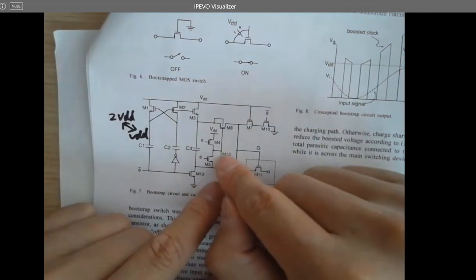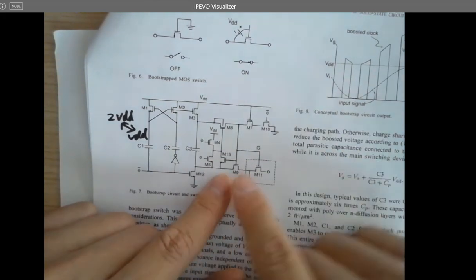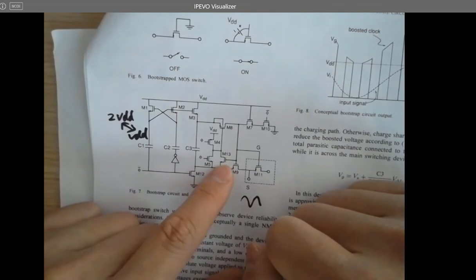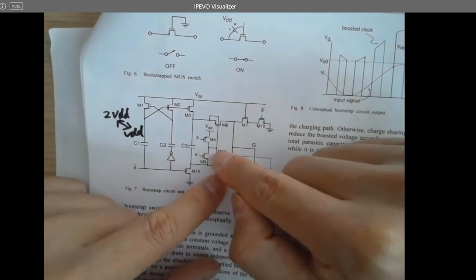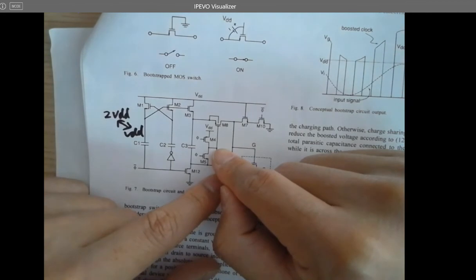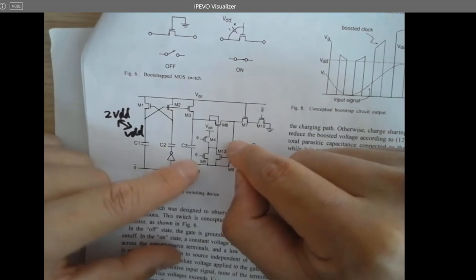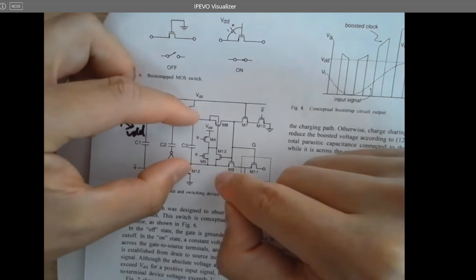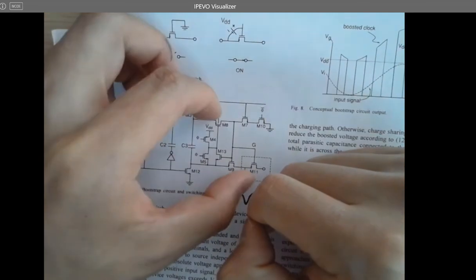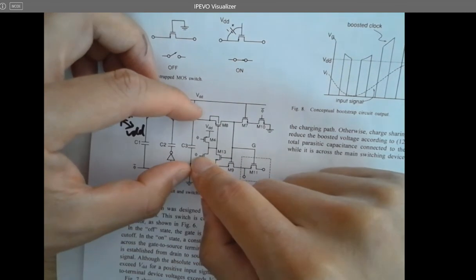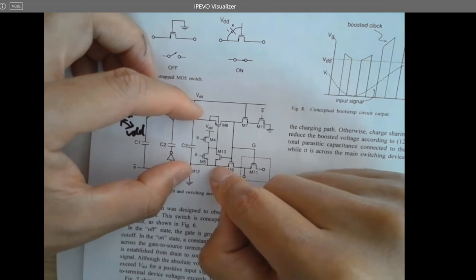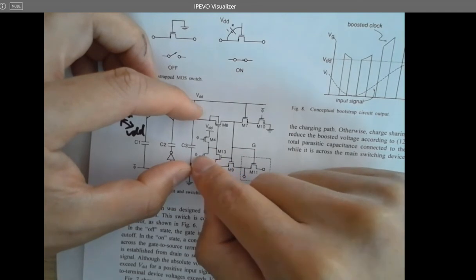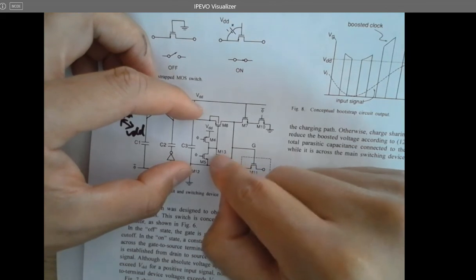So what's the function of this guy? It seems like it's not doing anything. Keep in mind, the voltage here can be higher, and I'm willing to pass everything from here to here. So I can directly connect these two terminals to these two terminals. But the gate voltage for this NMOS is not high enough to do it. So I need a higher gate voltage to connect this pin to this pin, to pull it down to this pin. This guy cannot do the job because sometimes it's higher than the clock voltage high. So I need a higher gate voltage to do that. So this transistor will do the job.